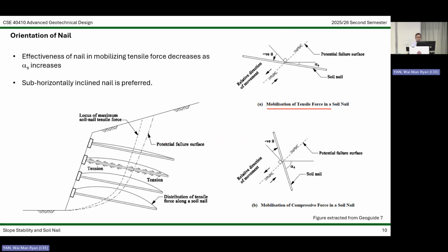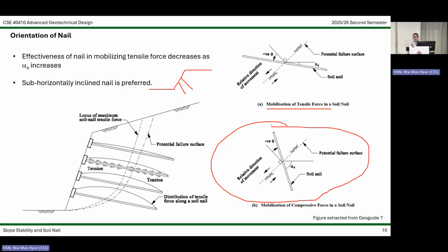On the other hand, if the nail is constructed like this, very subvertical, then we get something like this to happen. And if that happens, the tensile force cannot be mobilized along the nail. It instead mobilizes the compression force, which is something that we don't want. Okay.